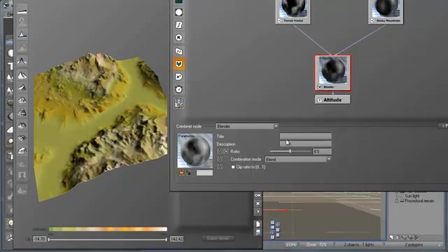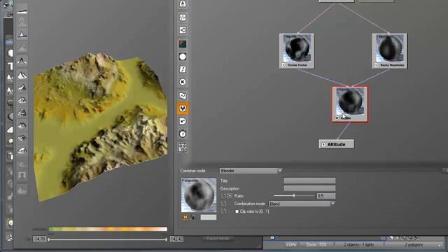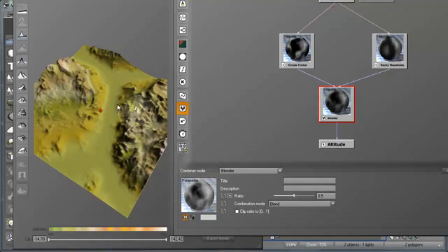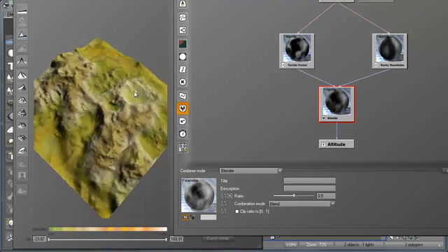Here it is, and I'm going to explain rapidly because it's very easy to understand and use. Here you can add a title or description if you want to, pretty self-explanatory. And here we have the ratio where we blend or mix our two terrains. I'm going to leave it at 0.5, which means 50% of the terrain fractal and 50% of the rocky mountain. Let's see what we have. Wait for it to generate. Okay, here it is, pretty much a mix of the two terrains.